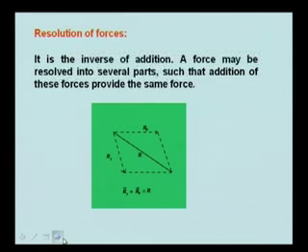Then we discuss the resolution of forces. The resolution is the inverse of addition, like two forces can be added to make the resultant. Similarly, a force can be resolved into two components or several components such that the addition of these forces provides the same force. So, whereas the resultant of forces is a unique vector, resolution of a force may give many solutions. Okay. However, if we fix the directions, then you may get a unique one.